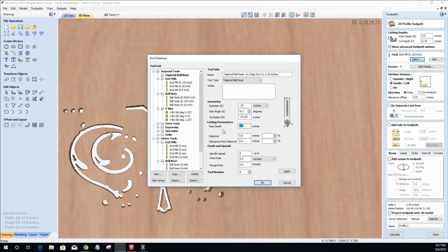And the pass depth on this. Now the ball nose end mills, 90% of the time, are generally used for 3D finish cuts, but they're also end mills. They can remove massive amounts of material, like a regular flat end mill. But we have an advantage with the sharp point to be able to get into those tight areas. But on my pass depth, I still don't want to be too aggressive with my end mill, so I'm just going to use a 1/8 inch pass depth on this.